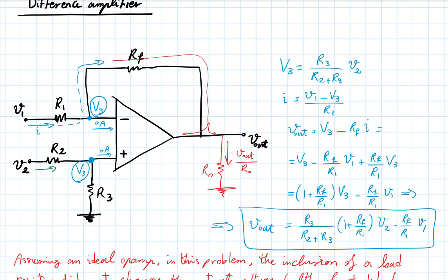I wouldn't do it. Good. Because what if that resistor is 1 ohm and the battery is 10 volts? That requires 10 amps, and the battery can supply only maybe half an amp, right? What will that do to the battery? It will drive it way above its current limit, probably heat it up, at the very least damage it, drain it, or worse things could happen. So you don't do that.